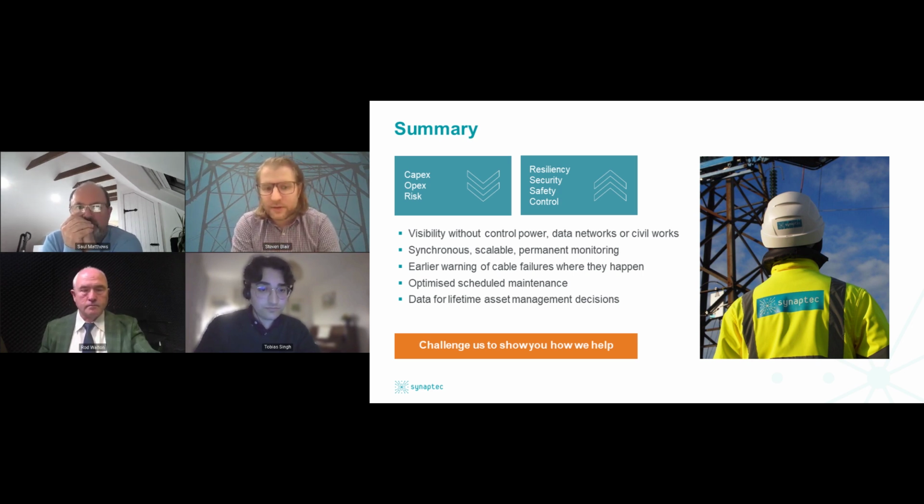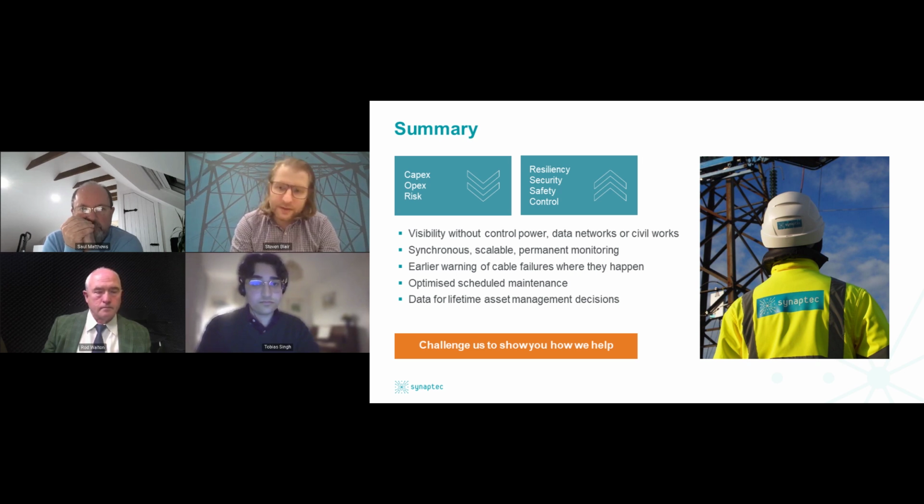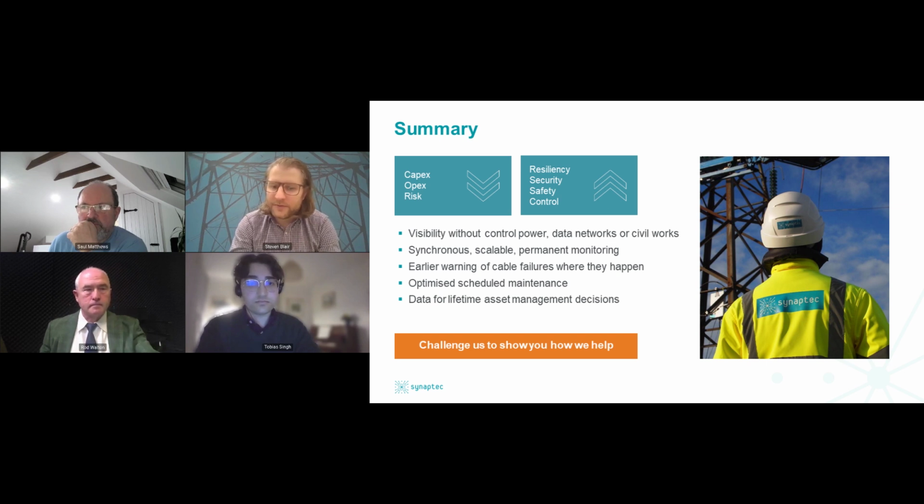So obviously there might, for a high voltage grid cable, like I showed earlier, there's a cyclical nature to the load on that cable over a day. And there'll also be different variations throughout the seasons, throughout the year. So we take care to subtract those benign, normal variations from the behavior of the system to be able to detect what's a true anomaly.